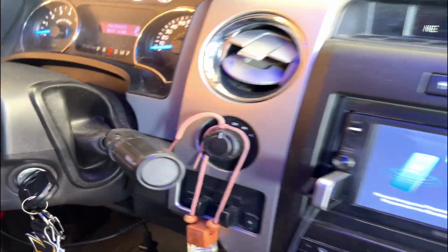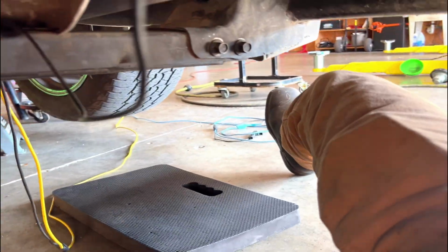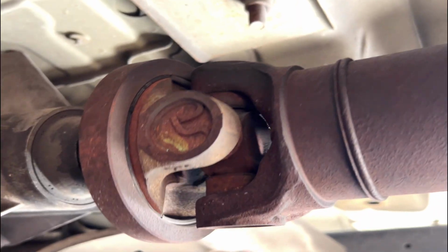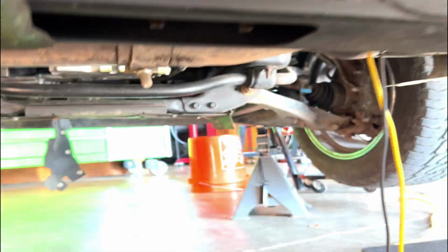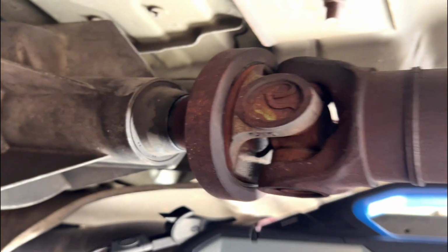and I'm going to do my best to duplicate it, so pay attention to this. All right, right off the bat, shifter is in two-wheel drive. Let's go ahead and roll under this old thing to the best of my ability. And right now, this is a rear drive shaft. It spins. Front wheels do not move. Front drive shaft does not move. I'm spinning it. So we are in true two-wheel drive.